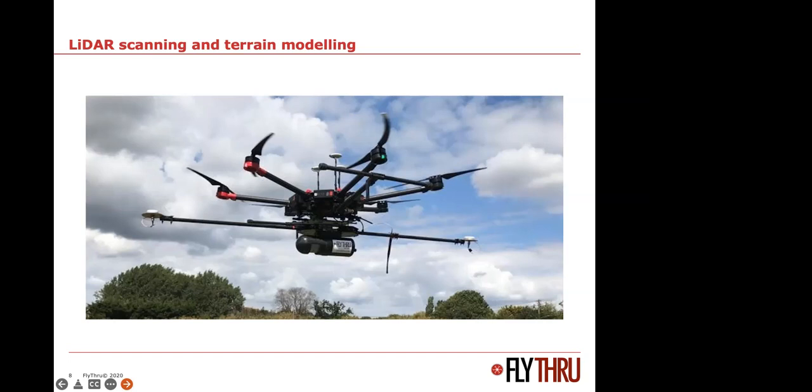So there are certain things that you have to know beyond the fact that you can pick up a phone or a tablet now and press, that's where I want it to go. Wind is a massive consideration when collecting data, especially if you don't want blurred imagery, you don't want data that is taken beyond the capabilities of the sensor that you're flying with. So it's one of those things to consider when you're on site. You can't do it in advance. It's one of those things that you have to think about when you arrive on site.